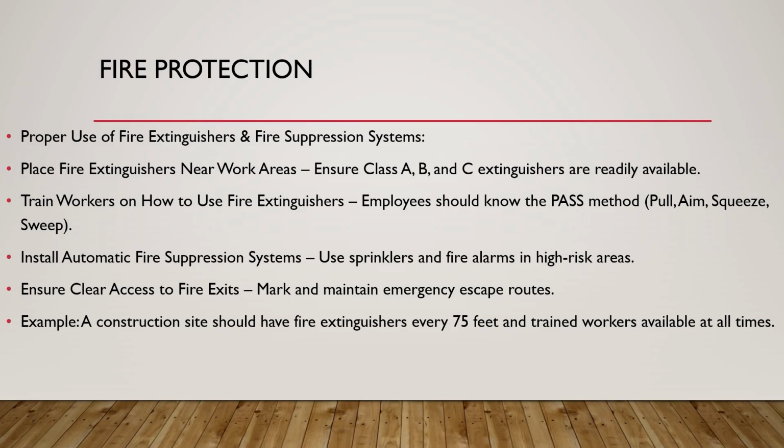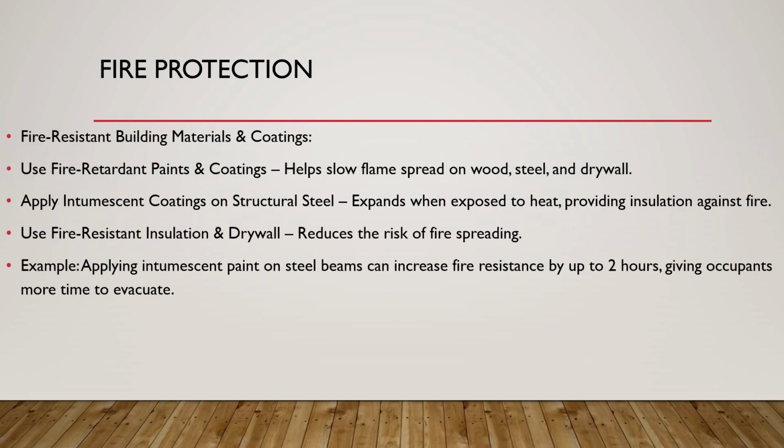Install automatic fire suppression systems. Use sprinklers and fire alarms in high risk areas. Ensure clear access to fire exits. Mark and maintain emergency escape routes. Remember, in construction, a site should have fire extinguishers every 75 feet and trained workers available at all times.